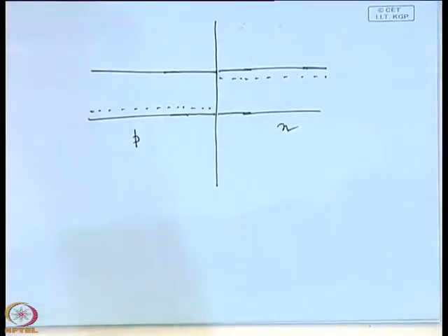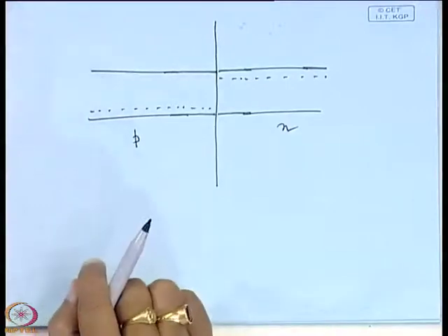Okay. Now, when you make the contact, what will happen? Fermi level will be constant, but why? It's not constant, we just take the Fermi level at equal. But why do you take it? Because no current flows between the two portions. If there is some difference, the charges flow from one to the other. Exactly, exactly. So, now what will first happen?